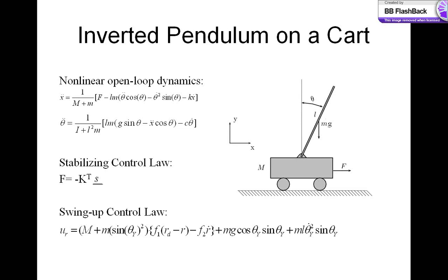upward position. For the swing up controller, first the mechanical energy is derived. Its derivative is computed, and consideration must be taken that its derivative must always be positive, so that its mechanical energy is always increasing. And also it was taken into consideration that the cart was bounded. The stabilizing controller used was pole placement with 4 poles, with the dominant closed loop poles having a high damping ratio of 0.9 and an oscillation frequency of 4.5 radians per second.